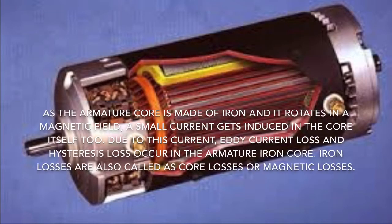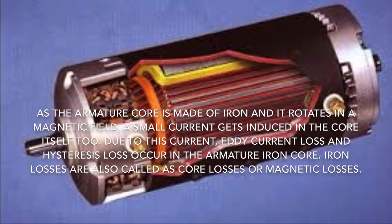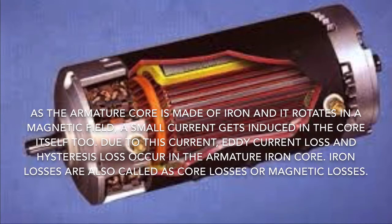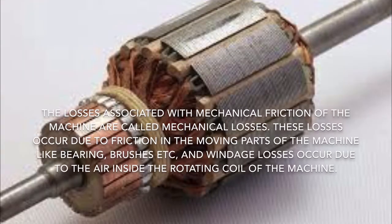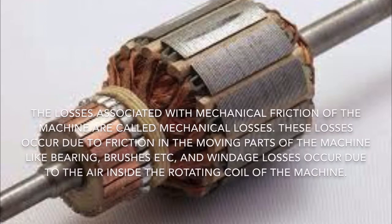Number 2, we got iron losses. Due to induction of current in the armature, eddy current losses and hysteresis loss occur. These losses are called core losses and magnetic losses. And number 3, mechanical losses. Losses which occur because of friction between the parts of a generator are called mechanical losses.